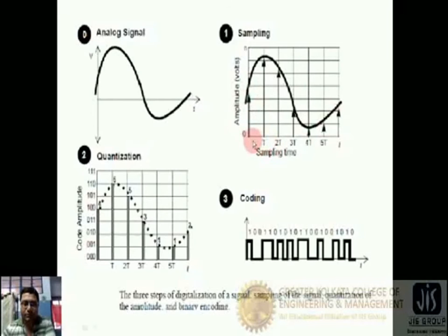Here we can see the three states that we have discussed. This signal is in the range of this level. We take this as a quantization level. This signal is slightly higher than this level, so we just put it down in this level. Similarly, this signal is like this, and in this way we represent the whole signal as a quantized signal.